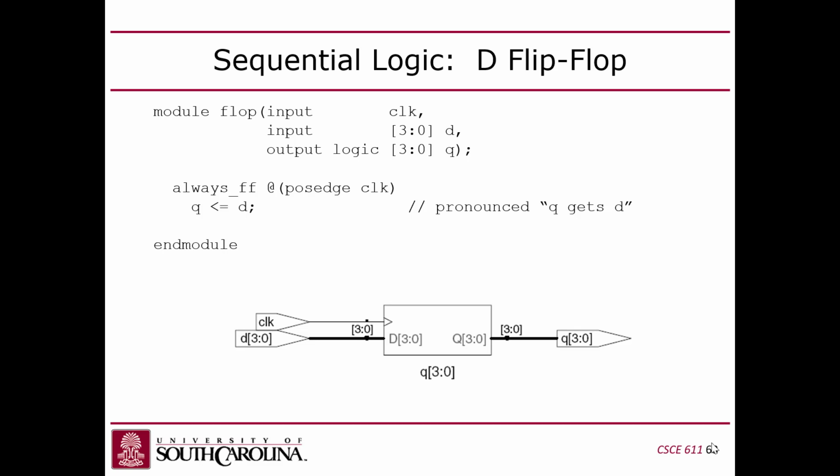So, you might have thought, well, so far I've showed you how to instantiate modules and connect wires to the inputs and outputs, and I showed you the assignment statement, the continuous assignment statement. But that's pretty simple. If you want to do something more complex, including if you want to do sequential logic, clock logic, you have to use this always statement. And we're going to give you code that you can try out with this.